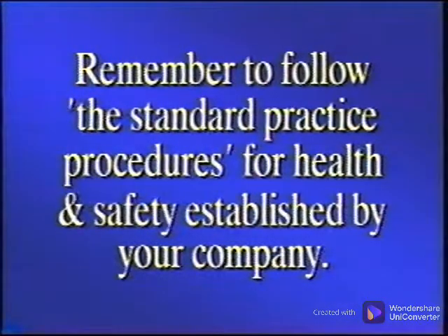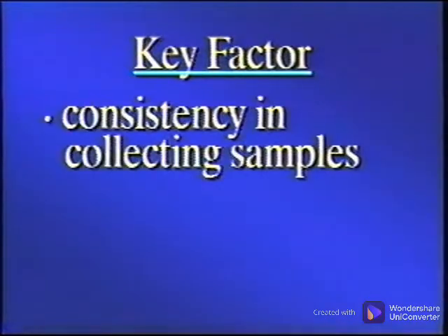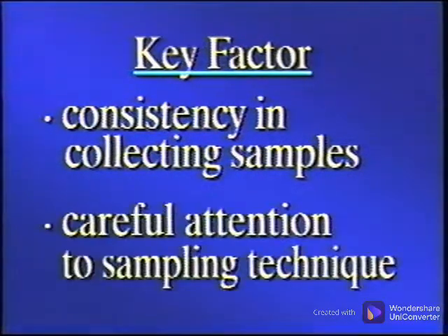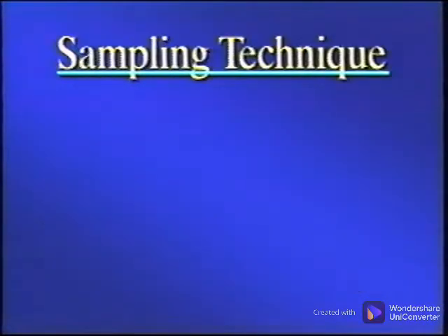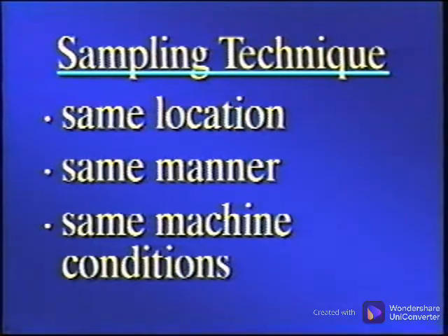When collecting oil samples or handling new or used oils, remember to follow the standard practice procedures for health and safety established by your company. A key factor in oil condition monitoring is consistency in collecting samples. Any oil monitoring program will fail if careful attention is not paid to sampling technique. For that reason, sample from the same location in the same manner and under the same machine conditions.